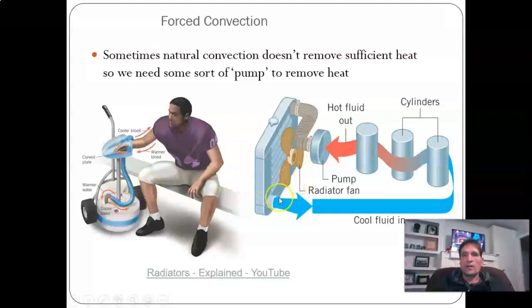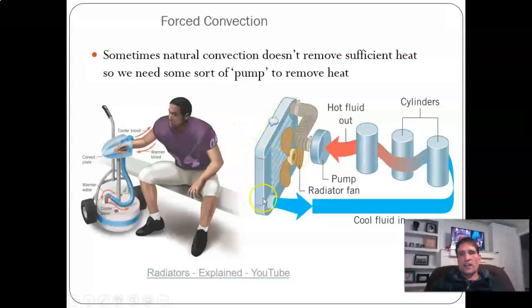And it's very similar to a radiator in your car, which carries heat away from the warm engine through a moving fluid, a coolant. The coolant circulates through the engine block and carries away the heat generated by the engine. You've got this pump which forces the fluid through, goes through this radiator which has the fan running, and that fan, through convection, dissipates the heat, kicks out the heat, and then you have this cool. So basically you have cool water going through the engine, and that carries away the heat by forced convection.